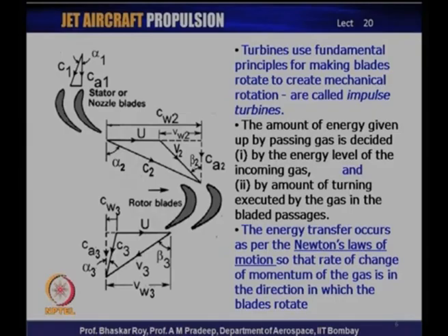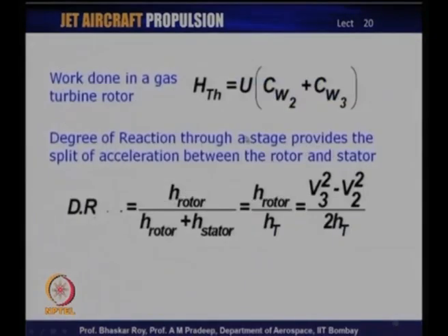So, we use those components which are measurable components and which are easily referred to the stationary components of the engine, and not the virtual or the relative components, which are of course understood by the designers, but they are not easily measurable quantities. So, we express them in terms of the measurable quantities.